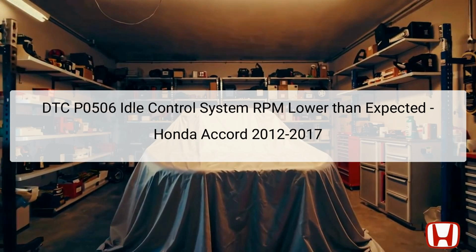If the actual RPM deviates significantly from the target RPM over a certain duration, it triggers the DTC. This deviation is monitored and managed by the Powertrain Control Module, PCM, which responds to various sensor inputs, including the throttle position sensors, TPS, accelerator pedal position, APP sensor, and other inputs that help maintain the correct idle speed. An idle speed that is lower than the expected threshold can lead to rough engine operation or stalling, making it necessary to troubleshoot the underlying issues to ensure proper vehicle performance.